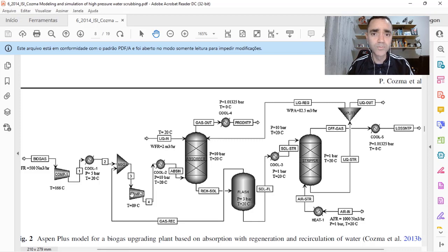So there are two things that can happen here. The first one is, if the discharge of the first stage of the compressor is 5 bar, it will seal the vapor phase of the flash tank, because the vapor phase of the flash tank is 3 bar, and I will not have enough energy to let my fluid go through the pipeline.